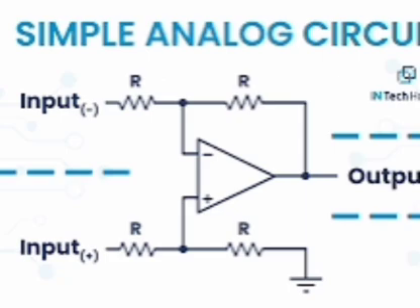Parameter VDC: half wave rectifier, Vm by pi; center tap based full wave rectifier, 2 Vm by pi; bridge circuit based full wave rectifier, 2 Vm by pi. IDC of half wave rectifier: Im by pi equals VDC by Rs plus Rf plus RL. Center tapped based full wave rectifier: IDC equals 2 Im by pi equals VDC by Rs by 2 plus Rf plus RL.